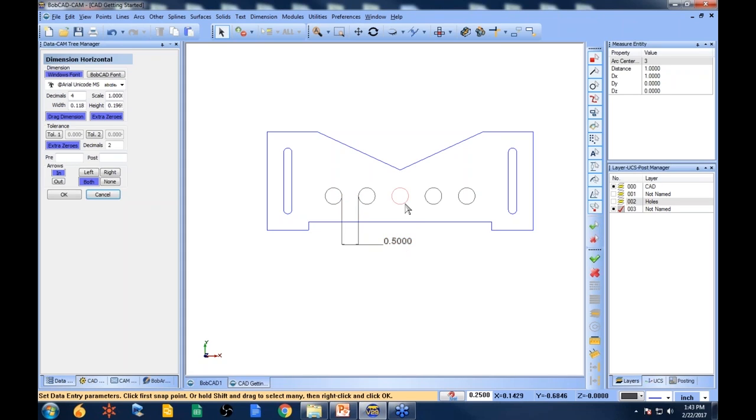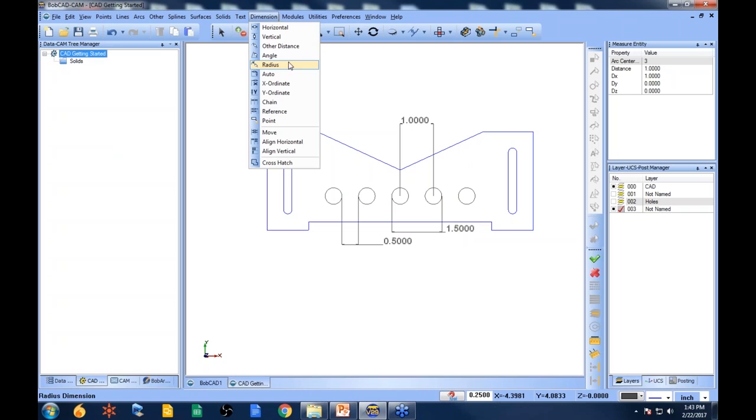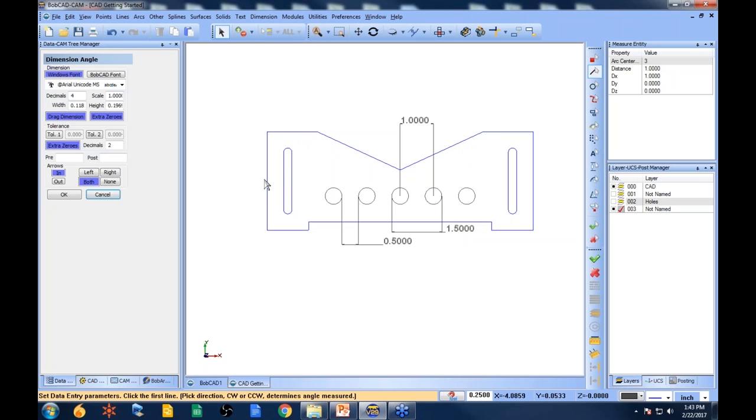So you can see I can measure. If I go from here to here, I can get this value, or I could go outside to outside, or what have you. All right, so again, this is for geometry that's flat in the XY plane. You can do things like, if you want to figure out what this angle is, you can go here to here, and depending on where you're at, sometimes you draw witness lines to get different angles to work off of, so you can figure things out. But yeah, you have your dimensioning tools, you have your inspection tools, and that's how you use your snap points as well.